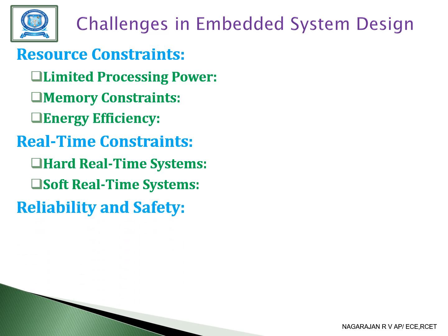Next challenge is reliability and safety. Fault tolerance. Embedded systems in critical applications must continue to operate correctly even in the presence of a fault. This requires designing for redundancy, error detection, and recovery mechanisms. Examples include using a watchdog timer to reset the system if it becomes unresponsive and implementing checksum verification for data integrity.